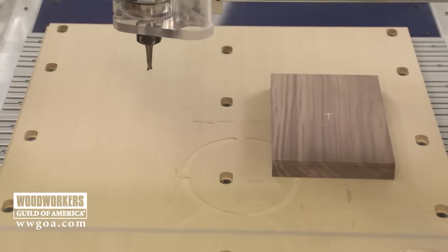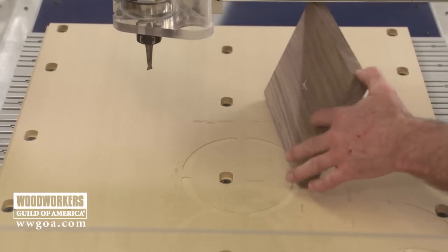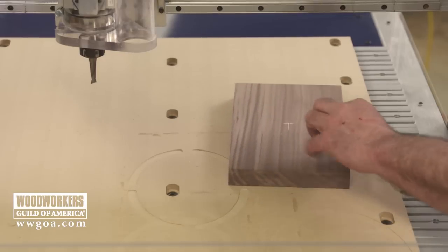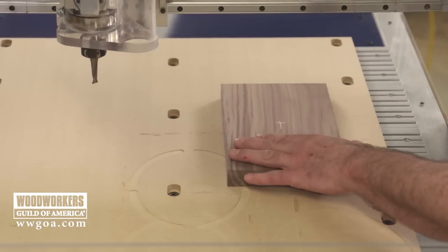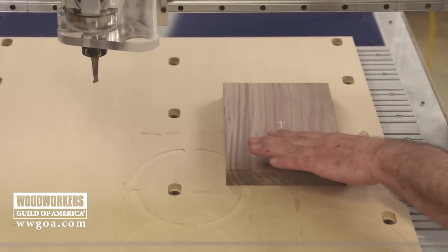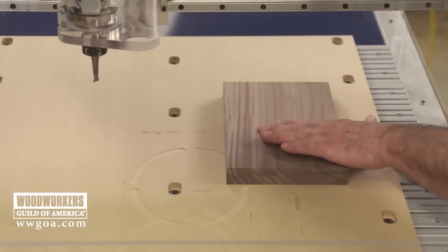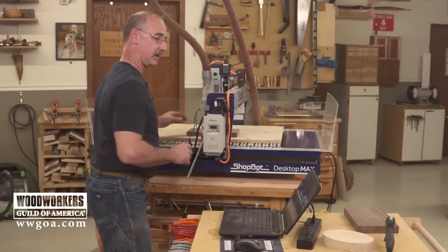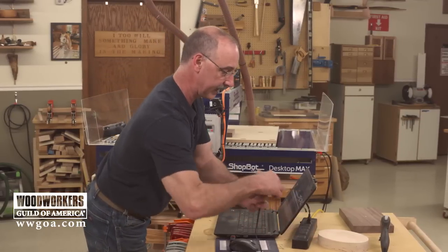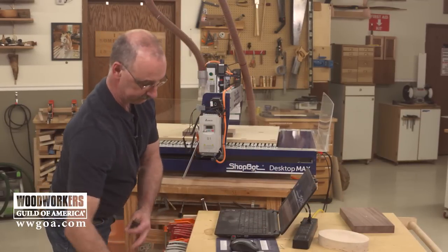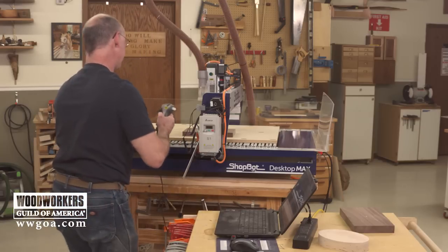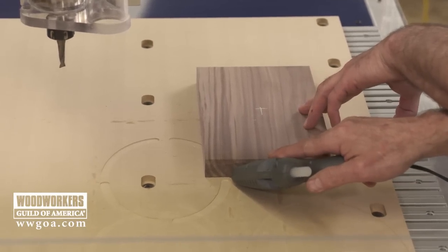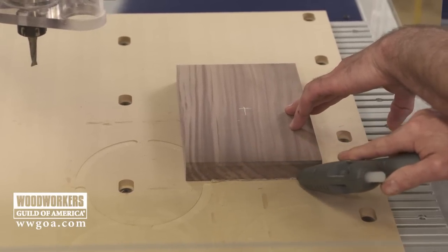Here's a great way to do this, hot glue. Now what I do not want to do is just simply put dabs of hot glue on the bottom and set this down, because if I don't get it perfectly mated to the spoil board, I might have high spots and low spots where this is a little bit canted. What works out nice instead is to use the hot glue kind of like a caulk gun, and I'm unplugging it just to give me some mobility here, and I'm going to run a bead of hot glue on the inside corner here.